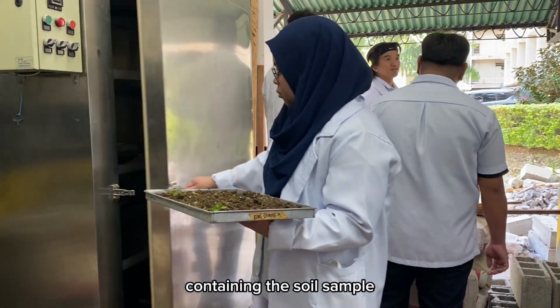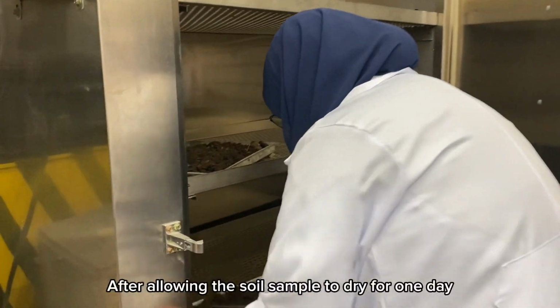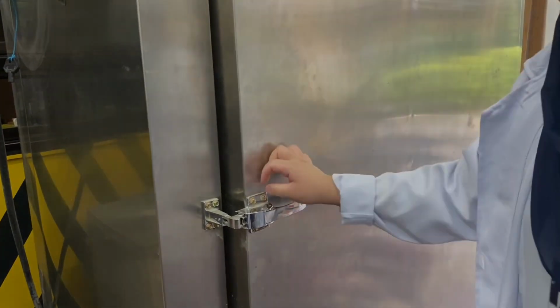Transfer the baking pan containing the soil sample into an oven for drying. After allowing the soil sample to dry for 1 day, remove it from the oven and measure its weight accurately.